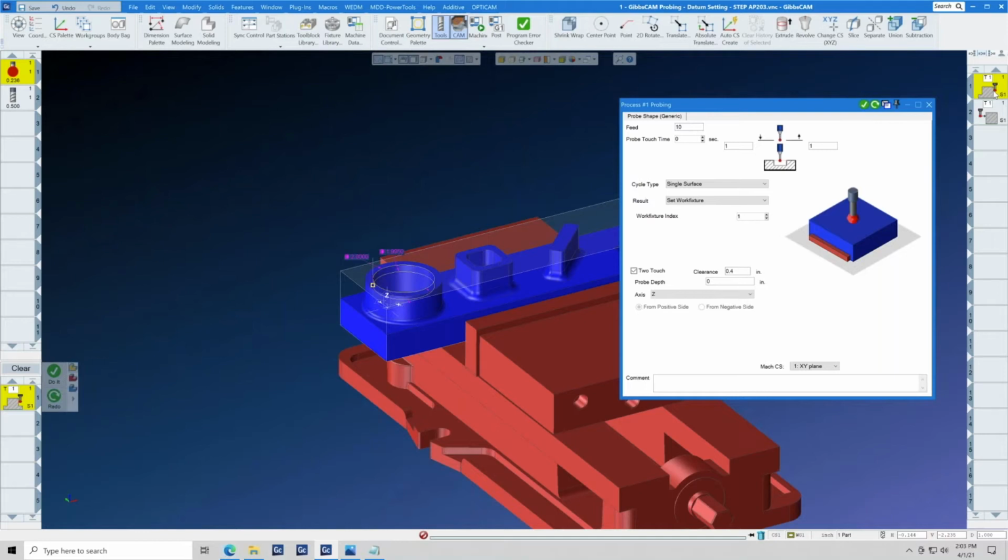The probe doesn't miss. Next, we want to introduce process stability and repeatability. When you integrate the probing into your machining process, the same thing happens from start to finish every time. You close the door, you push the green button. The probe goes in and finds the part very quickly without mistakes, and then the machining commences.